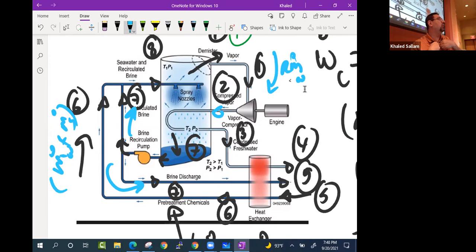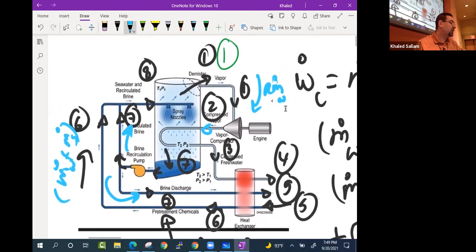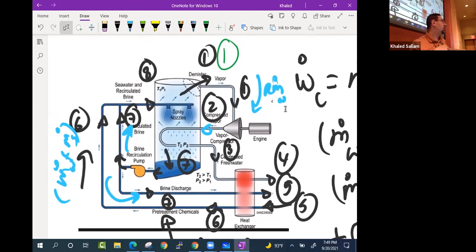So Robert is saying you can reduce the amount of system. He probably thinks there's not enough evaporation in one room, so maybe we need more rooms. It's basically the time the droplets stay in the air that determines how much they evaporate. If they don't spend enough time and leave quickly, m dot vapor, the one leaving up at 1, will not be much. So by circulating, you actually improve the residence time.